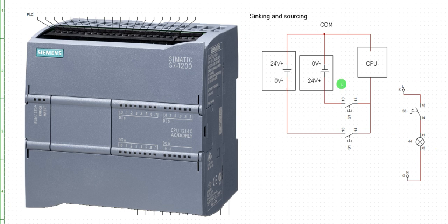Let me take this away so that I'll be able to simulate. Otherwise, this particular logic will not allow me to simulate, because this connection is not accepted in this software, because it's not a complete schematic. It does not have supply, no input here, no output. So it will not simulate.